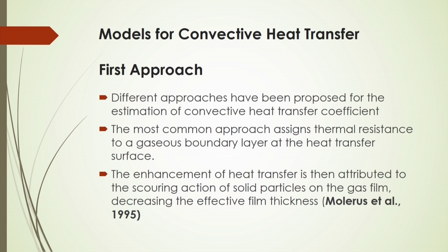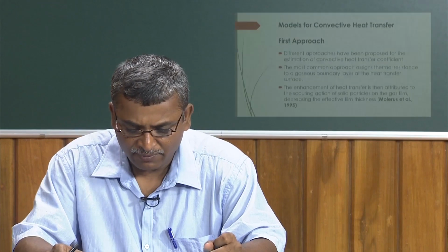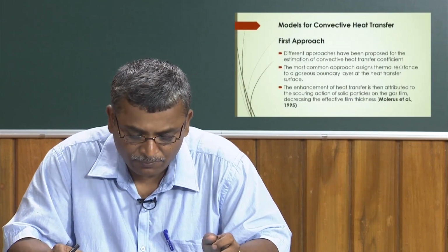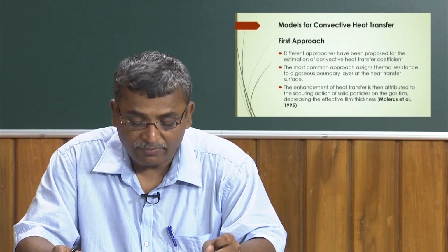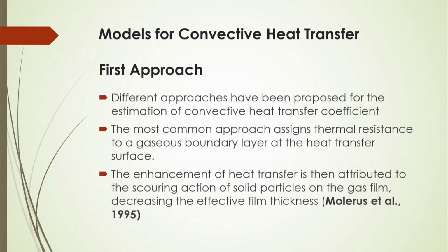The enhancement of the heat transfer is then attributed to the scouring action of solid particles on the gas film, which decreases the effective film thickness. So, the first approach demonstrates the enhancement of heat transfer in the bubbling fluidized bed by the scouring action of the solid particles on the gas film, which decreases the effective film thickness, and hence the heat transfer is enhanced.